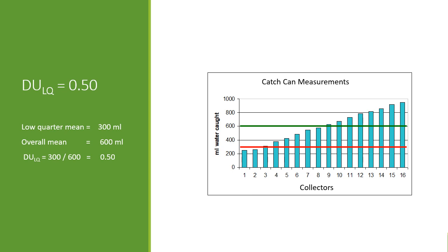So what does that mean if we try to apply 30 millimeters to 7/8 of our paddock? So same equation as before, 30 millimeters divided by 0.5 DU equals 60 millimeters. That's 30 millimeters of wastage. Twice as much water is being used to make sure that 7/8 of the crop is receiving 30 millimeters. What that means in reality is that bucket numbers 1 and 2 are still not achieving 30 millimeters, yet our other buckets, say 15 and 16, they're having twice as much water put on.